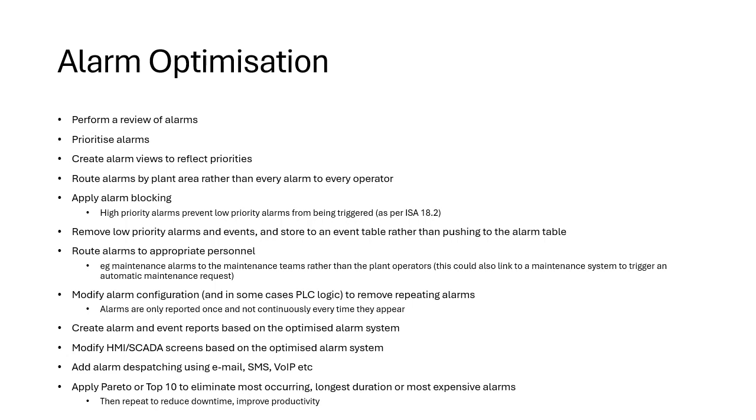Then you also have orange for warning states. There may be green, and there may be different shades of green depending whereabouts the process needs to be. That might be appropriate for a detailed screen, but you don't want to see that at a high level screen. So you modify your HMI SCADA screens to make them suitable for the standard operator conditions and to avoid overloading the operator.